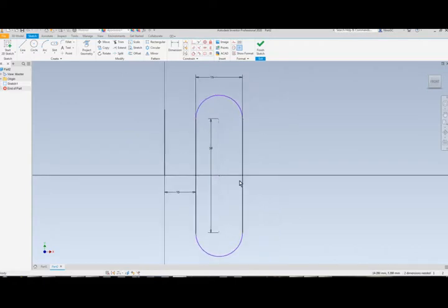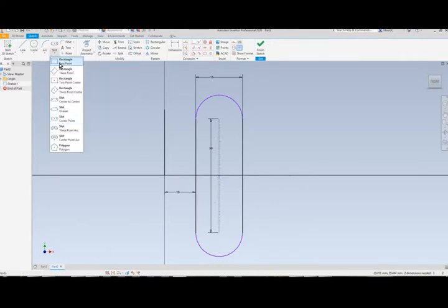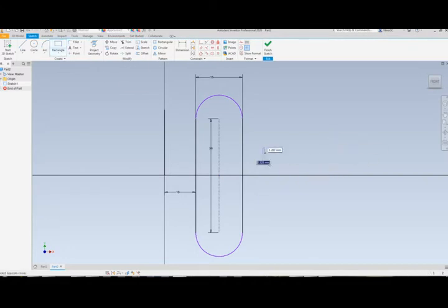So in the slot, let's do this. I'm going to create a rectangle. Now the rectangle is purposely outside of the slot. I'm going to grab this edge and pull it inwards, and I'll do the same thing here. What I want to do is make this rectangle centered to this line.